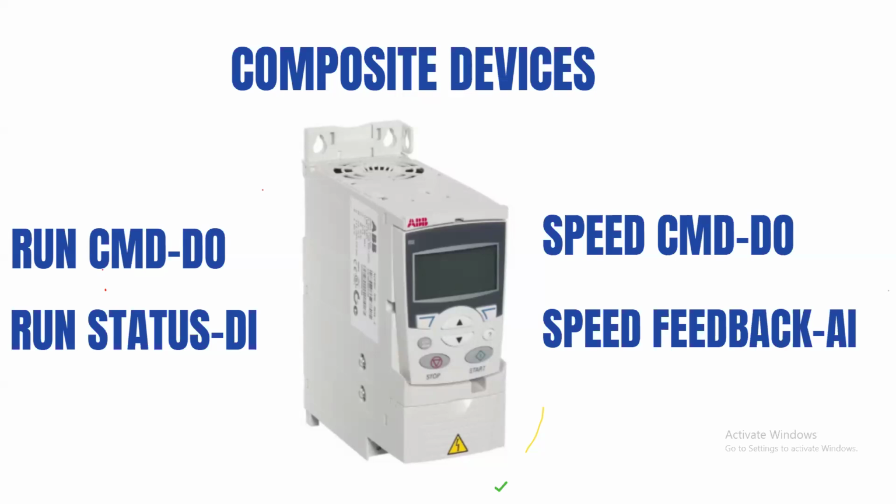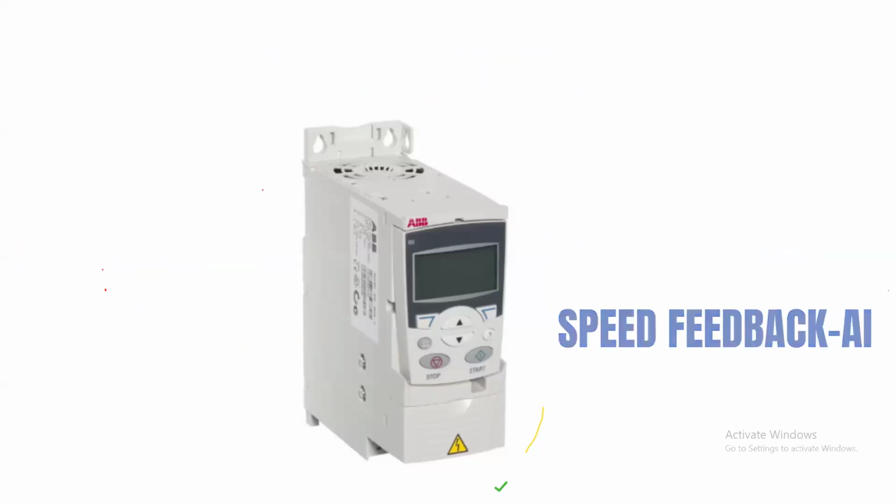So what I can say is that it all depends. The only thing you can know is that your contactor has latched. And if that contactor latches, you can use the auxiliary contact on your contactor, which you can feed back to your PLC. So if you are not going to use VFDs or anything like that, if the contactor latches, the auxiliary contact, some of them have normally open, some of them have normally closed contact. Well, I've not explained that, but the auxiliary contact can be wired back to the PLC. I think that's the simplest way to achieve what you mentioned.